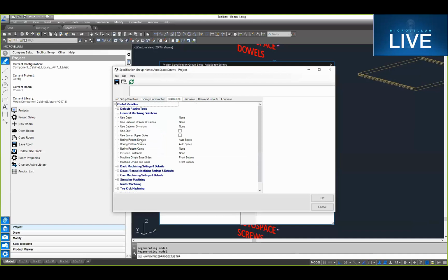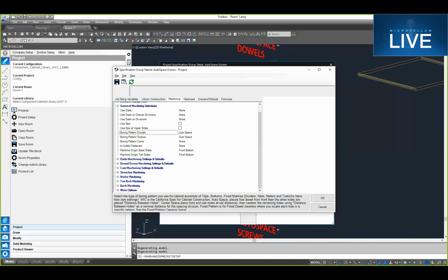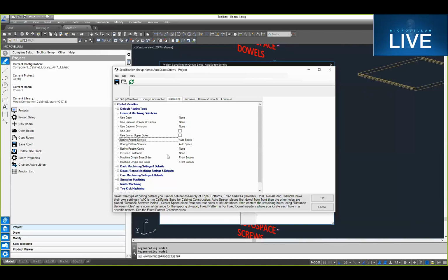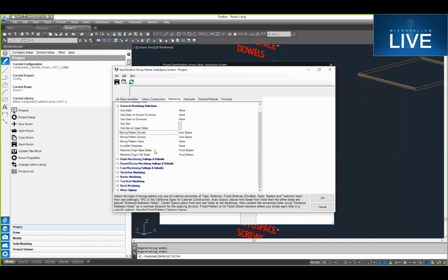you can see here that we've got both dowels and screws turned on. And this is certainly something that you could do. Even if you weren't doing it for this reason, you might alternate those dowels and screws. So put some dowels and some screws into your products. You could certainly do that. In this case, though, I'm just turning those patterns on so that in the case where I do have a finished end, it's going to turn those dowels on in place of my finished ends there.